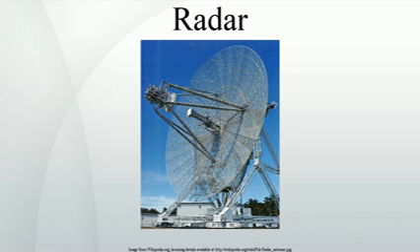Jamming. Radar jamming refers to radio frequency signals originating from sources outside the radar, transmitting in the radar's frequency and thereby masking targets of interest. Jamming may be intentional, as with an electronic warfare tactic, or unintentional, as with friendly forces operating equipment that transmits using the same frequency range.